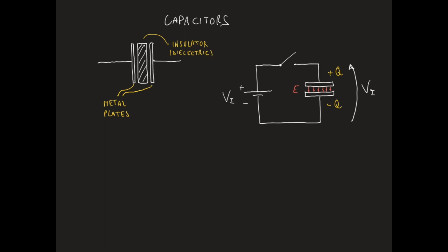In the case of a real capacitor, leakage currents or parasitic currents due, for example, to bad insulating material may discharge the capacitor. So, if we wait long enough, a real capacitor will discharge. If we want to quickly discharge a capacitor, we can connect the two plates using a wire.